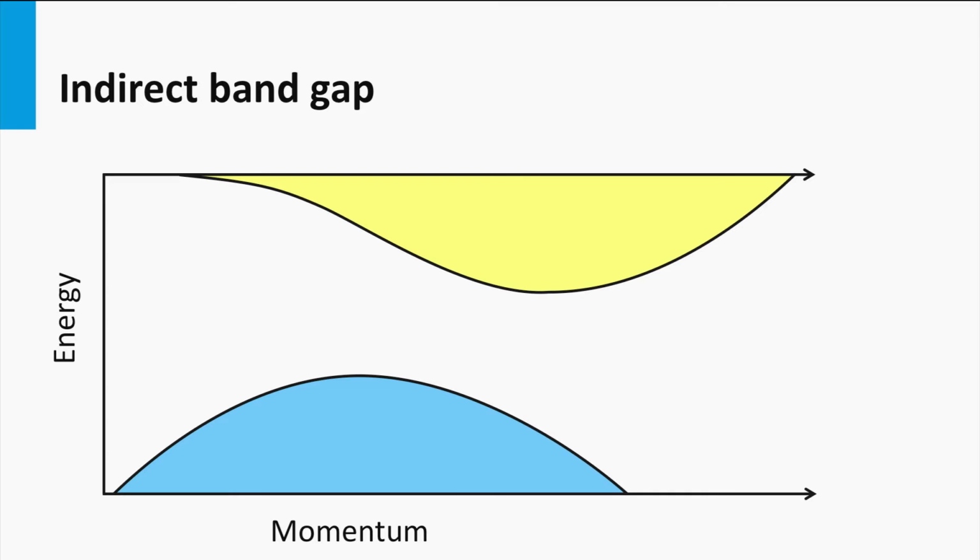On the vertical axis we have the energy state in the electronic bands. On the horizontal axis we have the momentum of the charge carrier. This momentum is also called the crystal momentum. Important to realize is that the position of the valence and conduction band may differ in different directions of the lattice coordination.